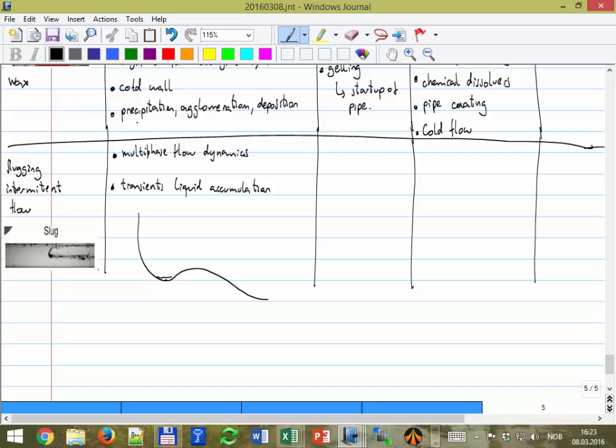It can be because of two things: the dynamics of multi-phase flow, or just because you have accumulation. You have accumulation, pressure buildup, production, then again accumulation, pressure buildup, production. Or people also call it blowout, but it's not the blowout from drilling, it's a liquid blowout.